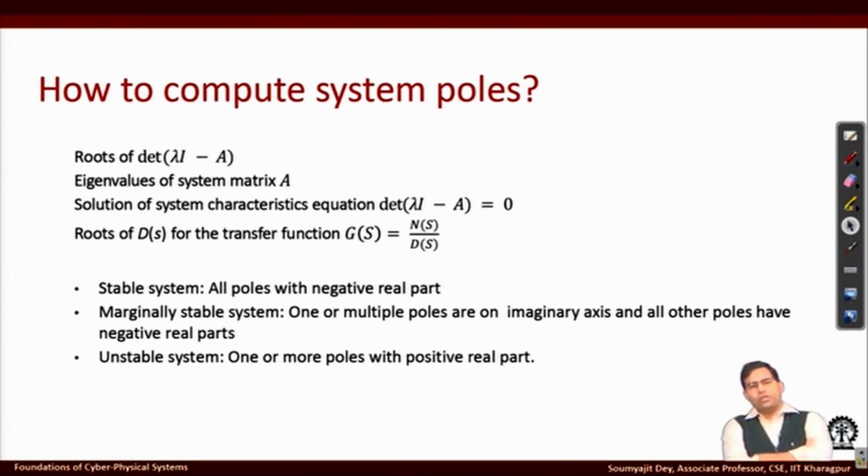You get the determinant polynomial, and you can set this to 0 for the characteristic equation, and then from that you can compute what the eigenvalues are. The roots that you compute from this characteristic equation are just the pole positions. So, again the condition is the same, it is just that you are starting from A instead of the transfer function representation here.